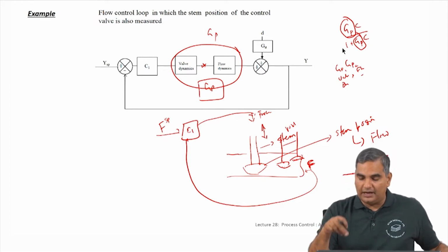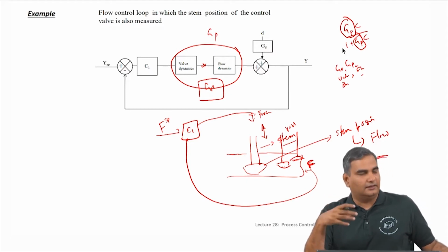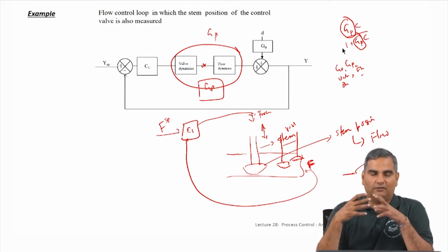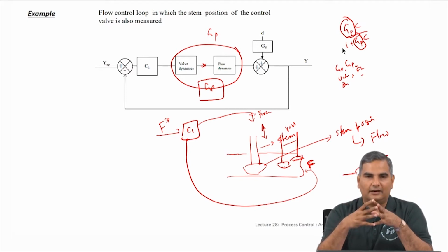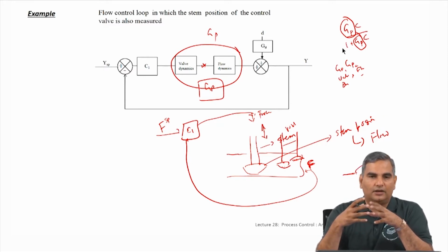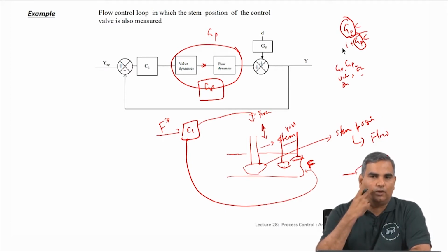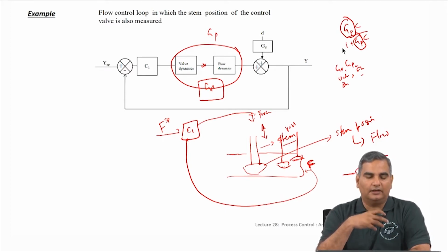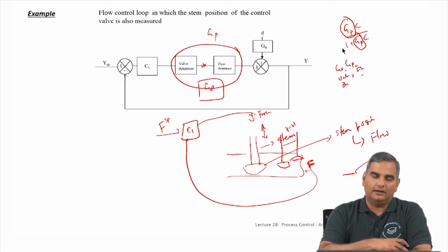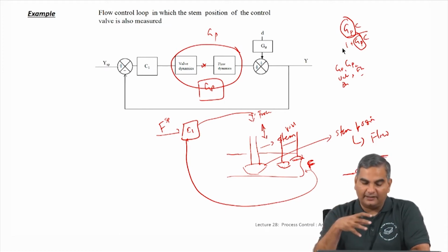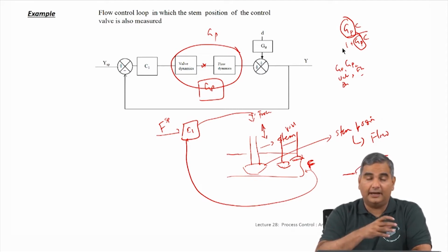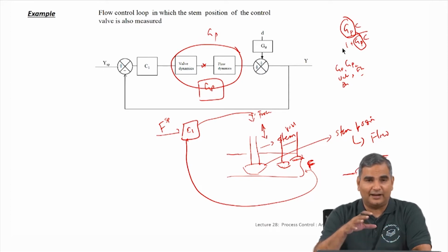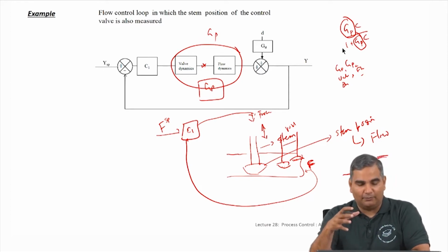And if you want to change the process transfer function, this is the kind of idea that comes up in more advanced control, where you have your standard design and then you design a controller and you are not happy with that controller performance. Then the only way in which you can improve the controller performance is through what we call redesign. So, you can redesign the process, or in this case we can redesign certain aspects of the process by adding a little more hardware and measurement. Any time you redesign the process, basically you are either adding or subtracting hardware and also adding more measurement.